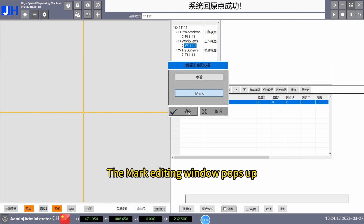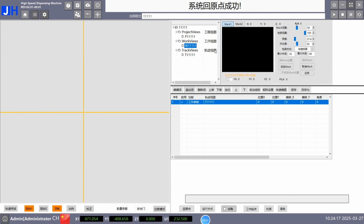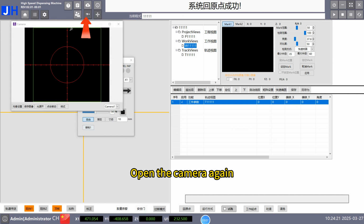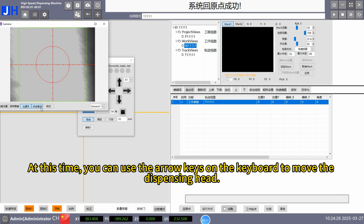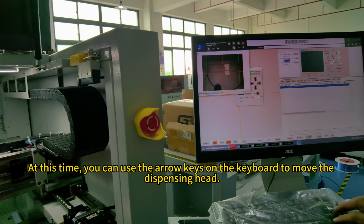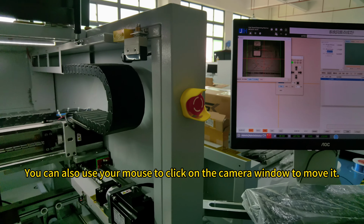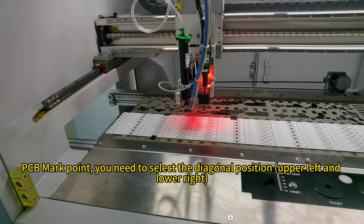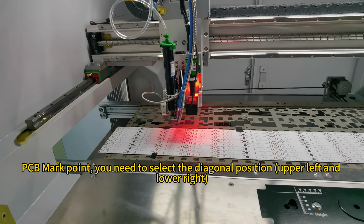The Mark Editing window pops up. 2 Mark Editing windows are displayed here. Then open the Manual Moving window. Open the camera again. Then click on the light source. Click Move to open. At this time, you can use the arrow keys on the keyboard to move the dispensing head. You can also use your mouse to click on the camera window to move it. For PCB mark points, you need to select the diagonal positions, upper left and lower right.